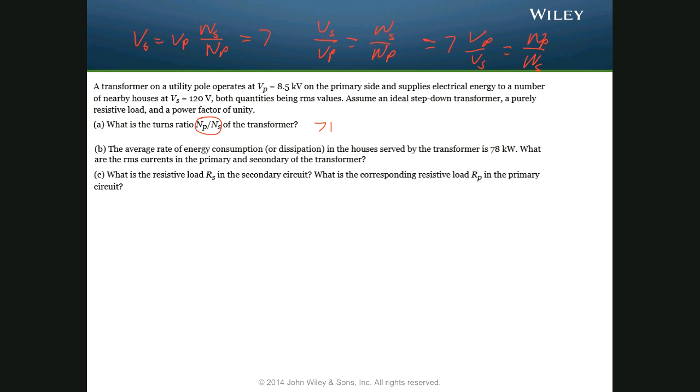Well, it asks for RMS, and we've been given stuff in RMS, so we know that P average equals I RMS times V RMS, and you have your RMS voltages here, so you should be able to unpack that by just solving for I RMS equals P average over V RMS. All right. So see what you get there.